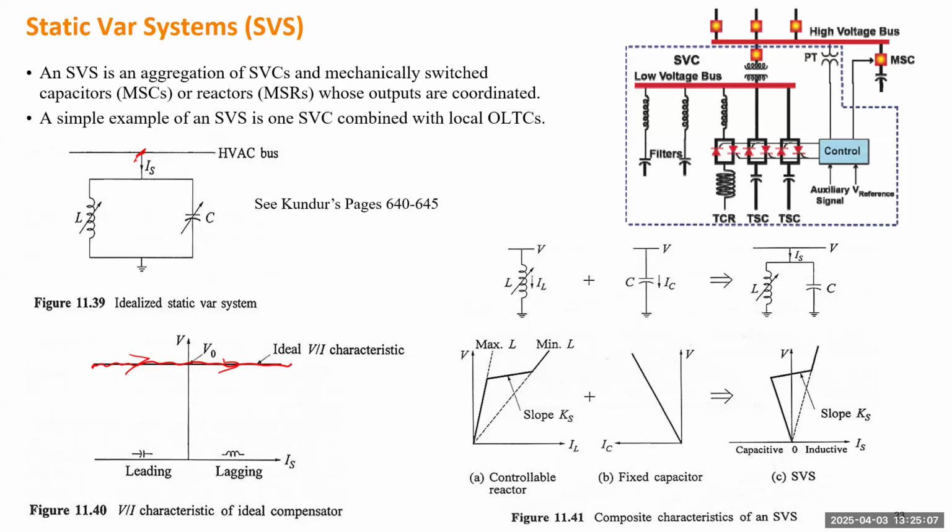I remember I went to a museum, they have a really high voltage capacitor. You can try. You have to push very hard to adjust the capacitance. It may be fine for an offline adjustment, but it's not good for automatic control. So a very practical idea is that I just have maybe a single capacitor, but I do have an adjustable reactor. An adjustable reactor is much easier. You're just sliding how much reactance you are going to put into the system.